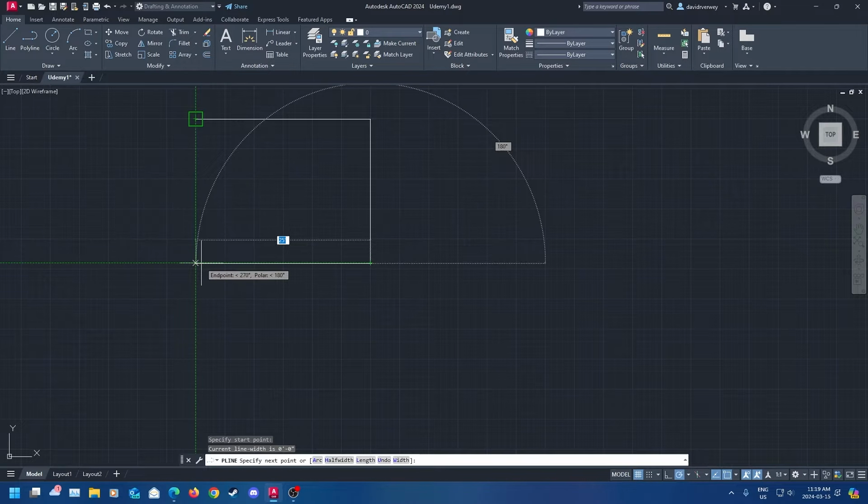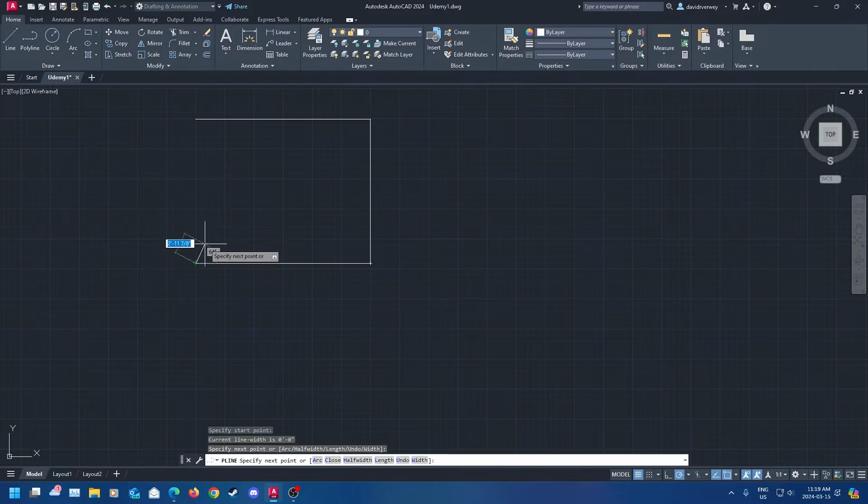As you can see on my screen, I have an x-axis and a y-axis green directional line showing me this is the point where it will be exactly the same length as the previous parallel line, and it's also lining up with the point where you started. So I can just click here and my line is perfectly in line with my other line, and there you have it.